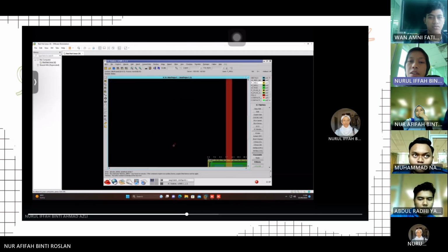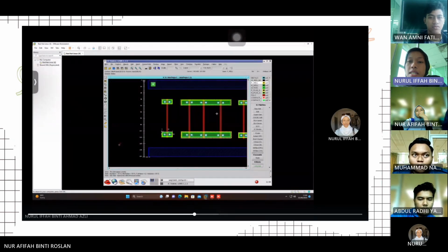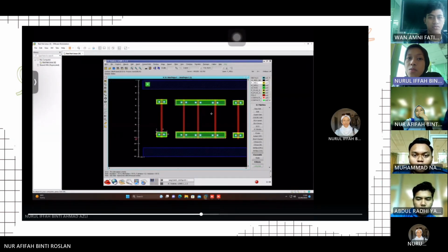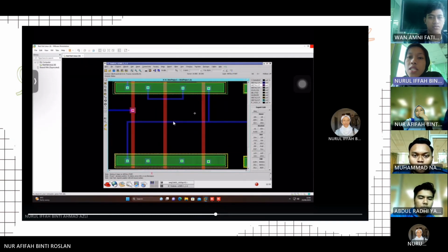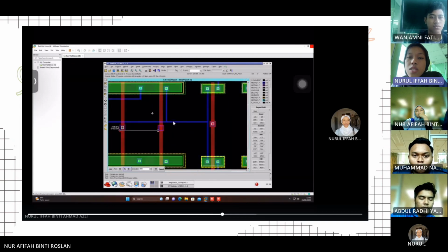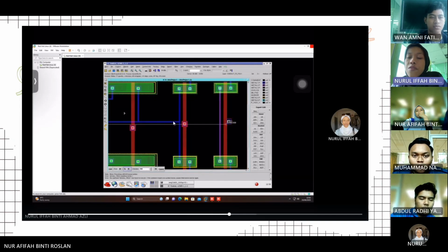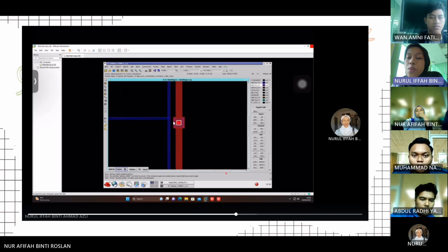I am checking the length to make it easier on the RC part. The length was stated by Najib just now. After connecting all the metal 1 to their own poly, as explained before in the layout sketching, I am putting metal 2 using a different metal, which is the purple one.